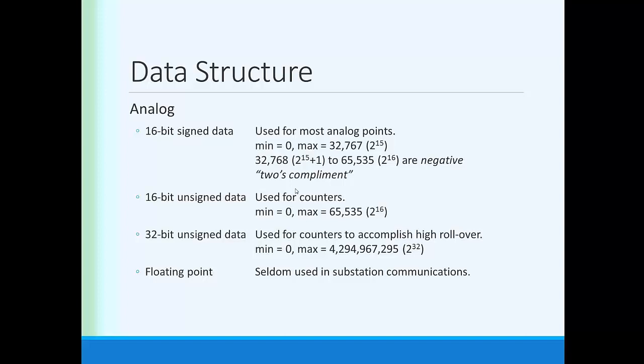Now, we would have to get out a chalkboard and do a little bit of rigorous math to explain why binary math works this way. But it's a method called 2's complement, which I would commend to you for further study. The basic idea is that if I take two 16-bit numbers, one of them negative and one of them positive, and I put one above the other on a chalkboard, and I add the bits, least significant bit, then the next bit, then the next bit, then the next bit, if these two numbers are equal in magnitude and opposite in sign, that should add to 0. The way that works is you use this method where the most significant bit is essentially your negative sign.